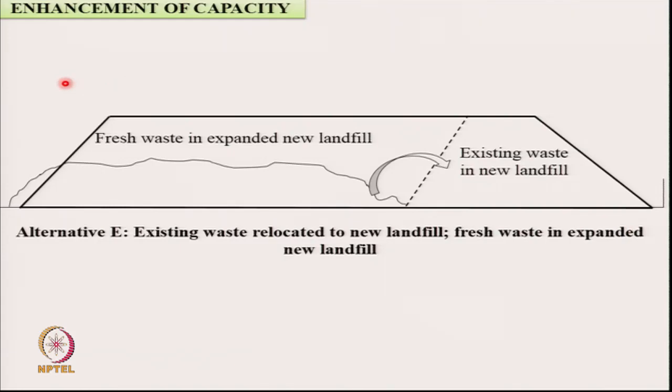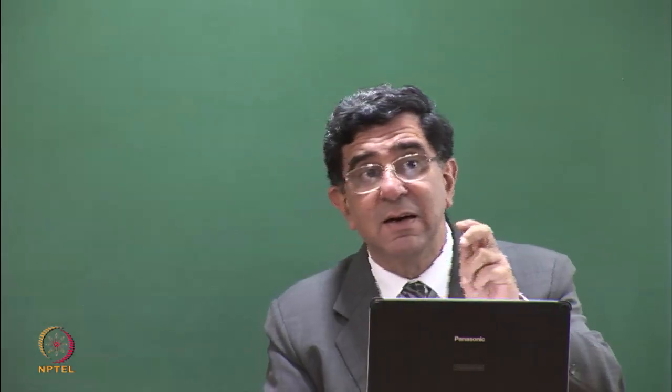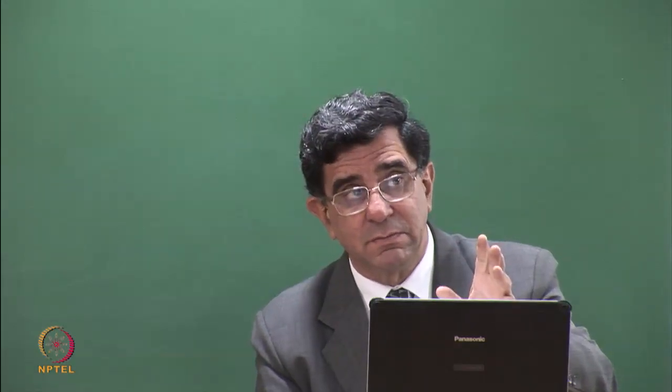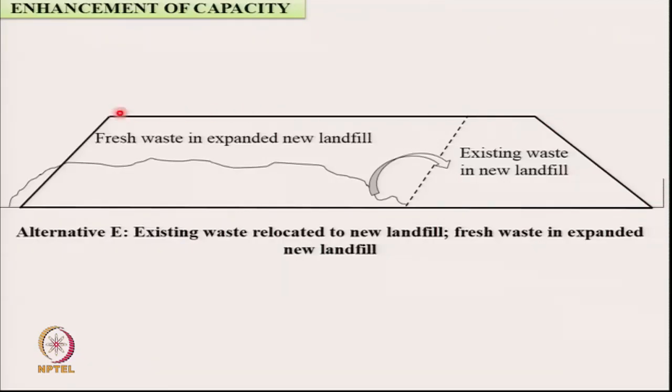Now any relocation of waste will create some odor. So the residents will complain while you are relocating the waste. Remember that. But it is something that you can do in 6 months. And then you have a completely, fully contained landfill. More expensive because you have to move all this waste from here to here.